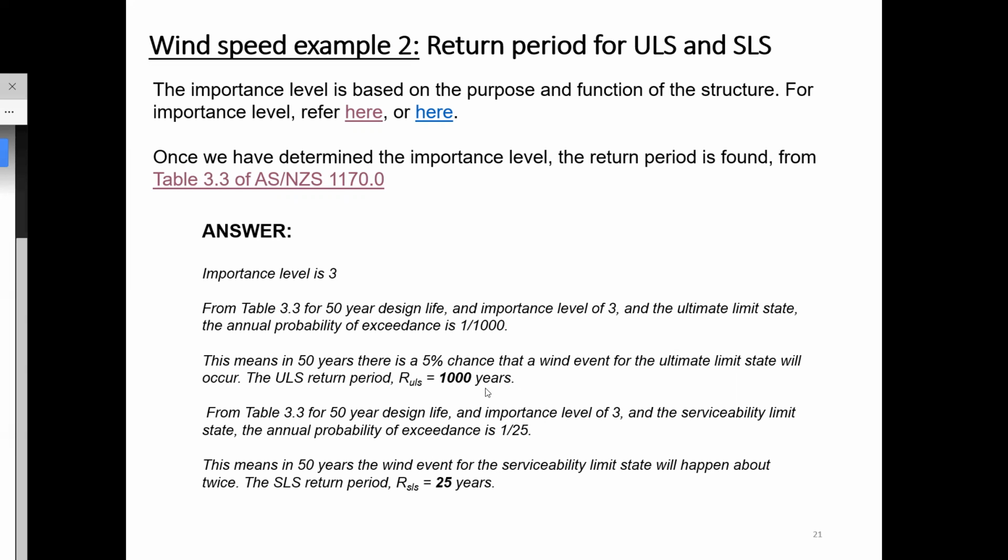This is not exact actually, how we just split it up, because for a 1,000-year wind, you could have 1,000 years where you don't have anything happen. It doesn't get to a probability of 1. If you have 2,000 years, you might have 2 winds which give you a 1,000-year return period, but those 2 winds might occur in the last 500 years.